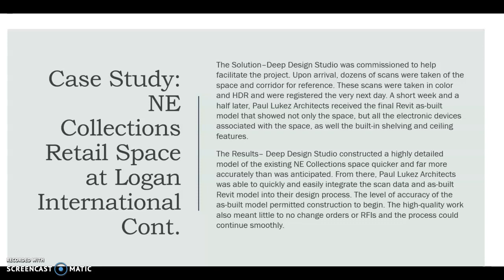So again, some people call it laser scanning, but really it's 3D high definition advanced camera scanning that can then turn into as-built models and several building information models, or BIMs, that you want to put it in. In this case, it was Revit, but I was also able to find some less successful scans in SketchUp and AutoCAD. It seems Revit is the most compatible with the technology thus far. So that rounds off the first one. We're going to go on to the next.